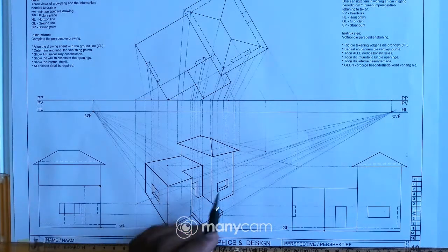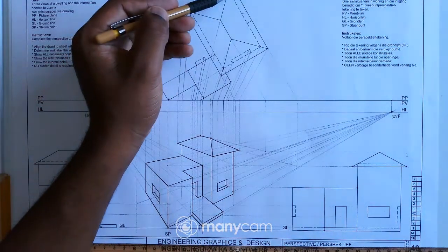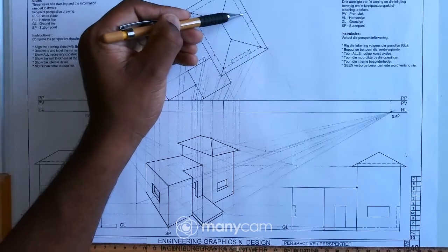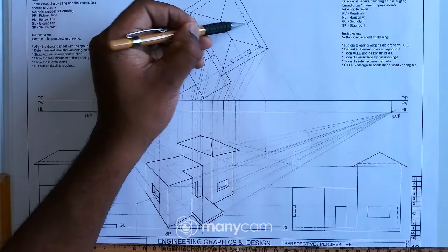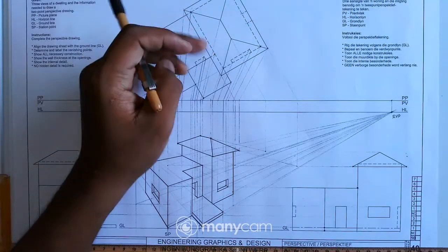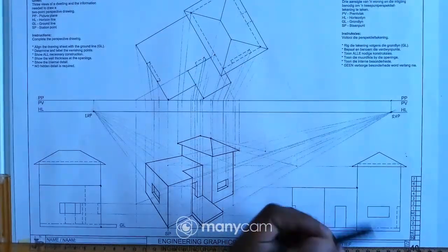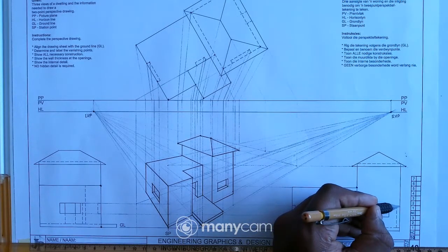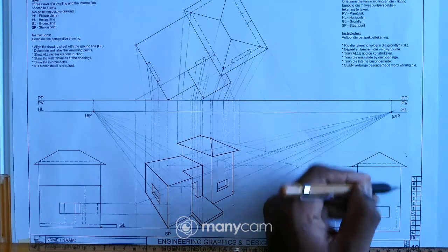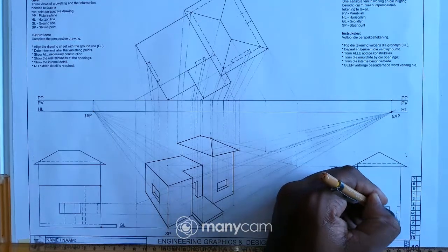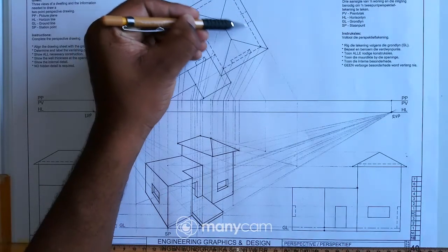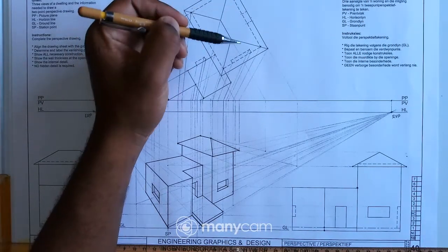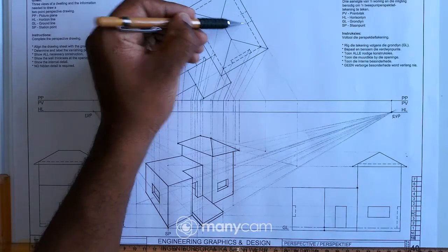For me to draw the edge inside there, if you check here, there's a mistake. This opening was supposed to be just inside, not outside. Why? Because if you check this elevation, the door opening is right there. This line, the outer line of the wall, is this one here, right? So we can't have the opening outside the wall, so the opening must be inside.